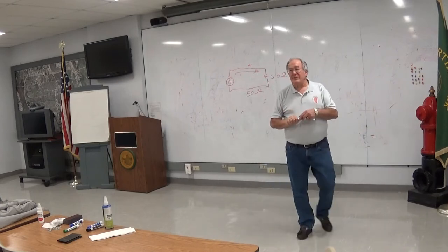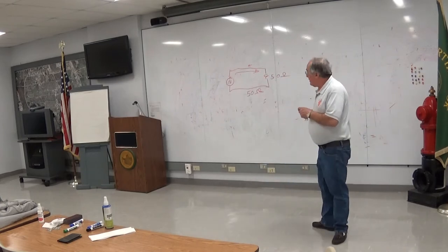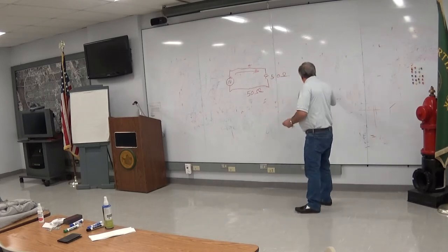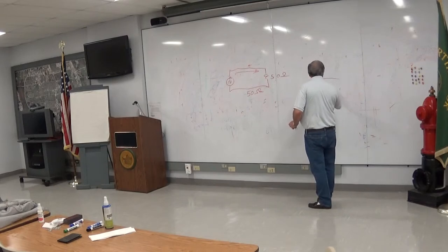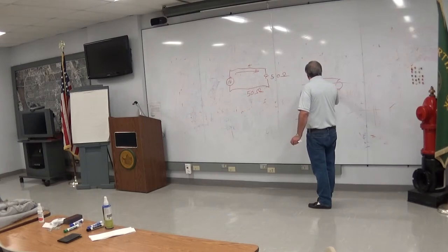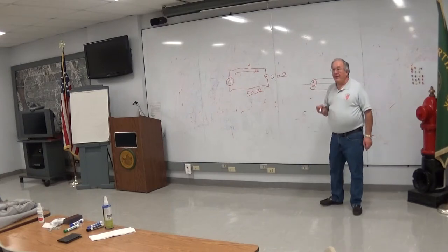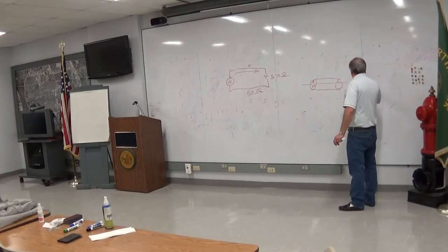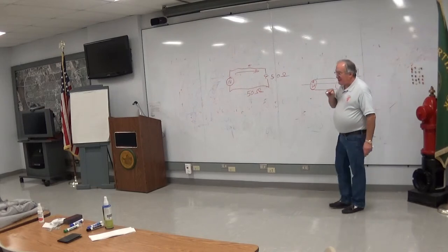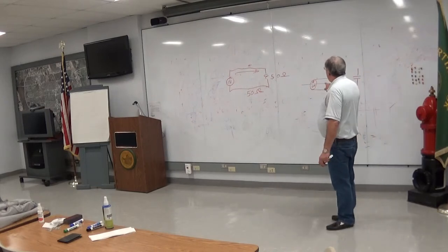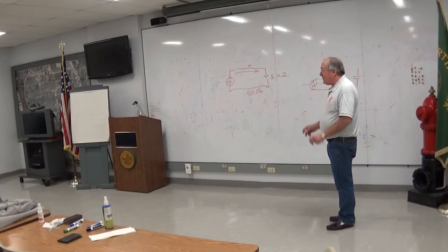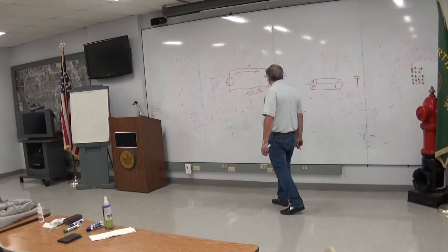In other words, the spacing between the conductors, the material in between those conductors to keep them apart, you know, remember the coax cable, you got this braided thing on the outside, and you got the cable in between. What's filling the space in between is some plastic material, polymer. It's called a dielectric. Dielectric, just like the dielectric between the plates of a capacitor, it means something that does not conduct electricity. And it's part of the equation that determines what is the characteristic impedance.